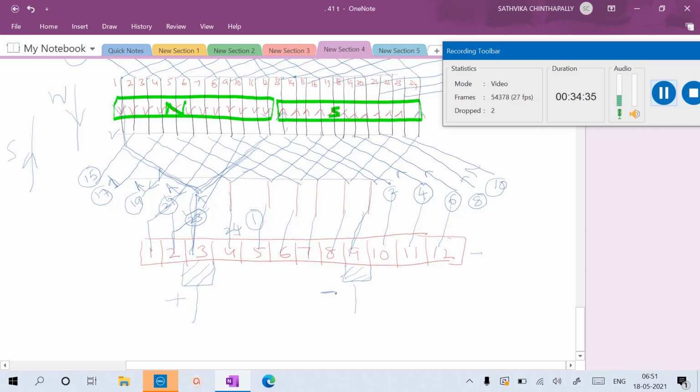So these are the conditions where, when the coil has both directions similar, you place one brush. Assume that if the current is coming towards the commutator, you take it as positive, and if the current direction is away from the commutator, then you take it as negative. So these are the brush positions. Okay, clear? So this is another step.